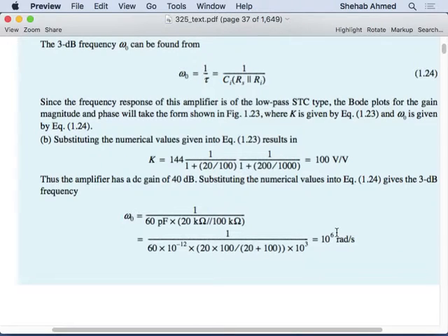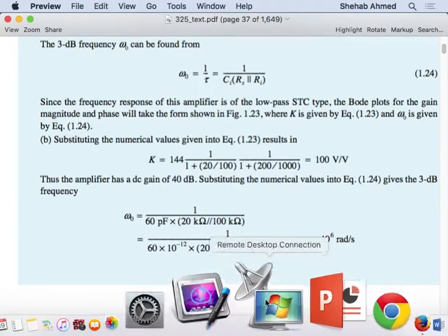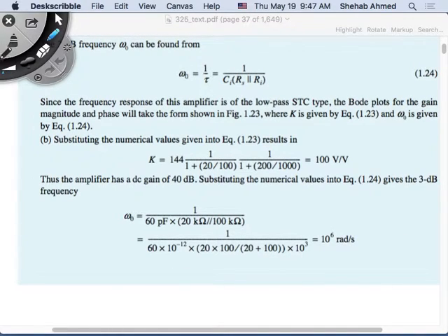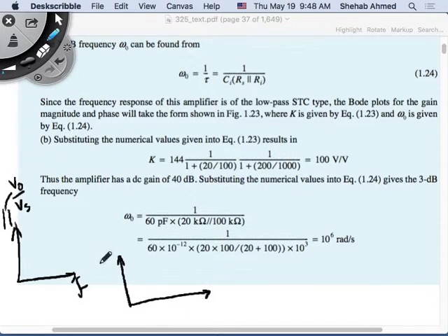So I want to plot the magnitude. Again, all I want to do is plot the magnitude of my transfer function, V output over Vs. I want to see what output I get when I have a certain sensor input. I want to do that versus frequency. And I want to see the effect of the amplifier on the phase shift of my transfer function.